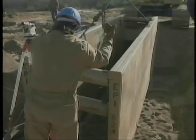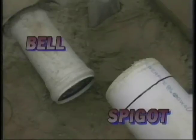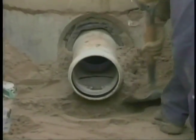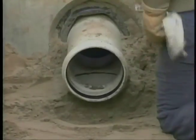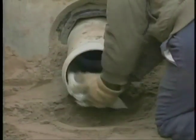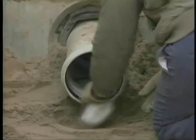Installation procedures are determined by the type of pipe. A standard procedure for installing PVC pipe is the bell and spigot method. A normal bell and spigot installation consists of these basic steps. The tailman digs a bell hole and cleans both bell and spigot ends of the pipe. He checks that the gasket is in place, then lubricates the bell, spigot, and gasket.